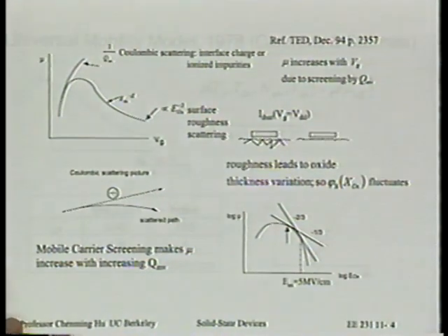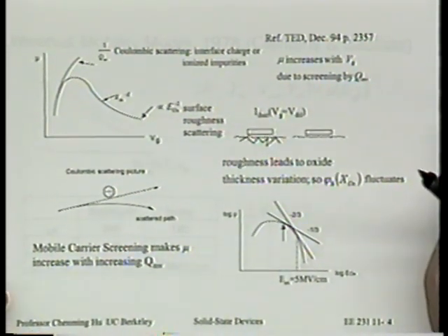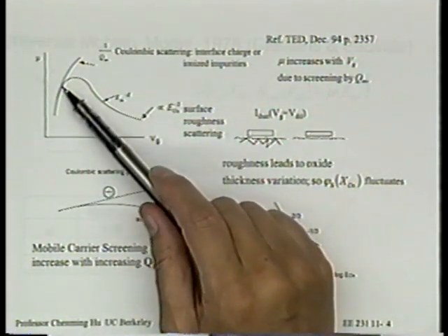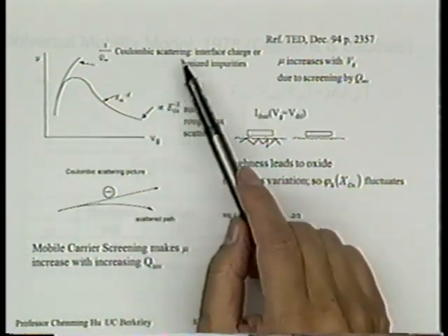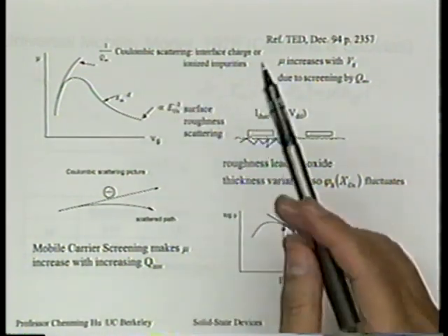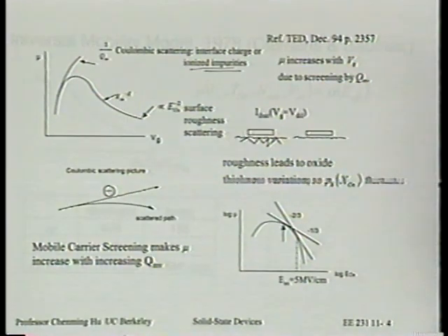Okay. So if you do that, let's say we now have a very good knowledge of the experimental data of mobility. It generally looks like this, in this shape. And in the interpretation, there's no dispute about what goes on here. This is the part that's least disputed: it's due to Coulombic scattering. Coulombic scattering can come from several sources. One is ionized impurities: just because the substrate has a doping concentration, there's dopant scattering.